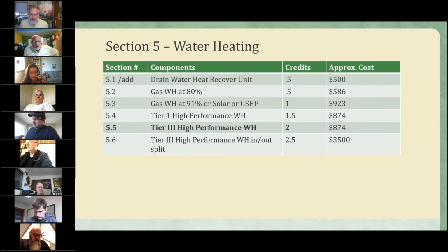Yeah, a little difference there. It's mostly off tubs and showers. It's not off every sink or anything like that. So your main drains, your tubs, showers, a lot of those tie in anyway to the same drain line. So on the tub showers is where you'd have to have those heat recovery coils or setups.